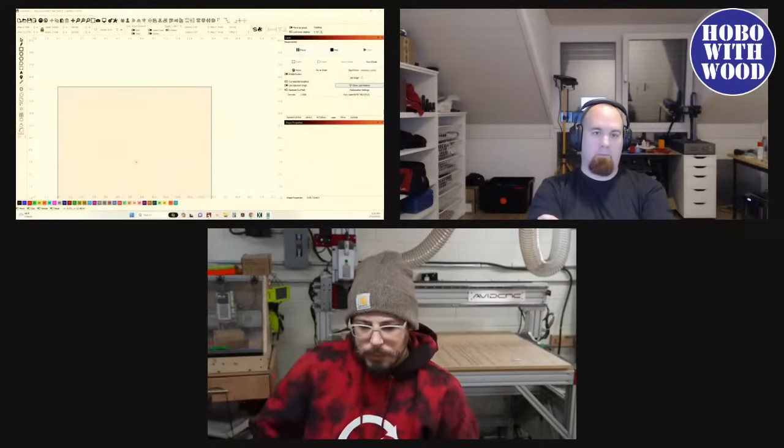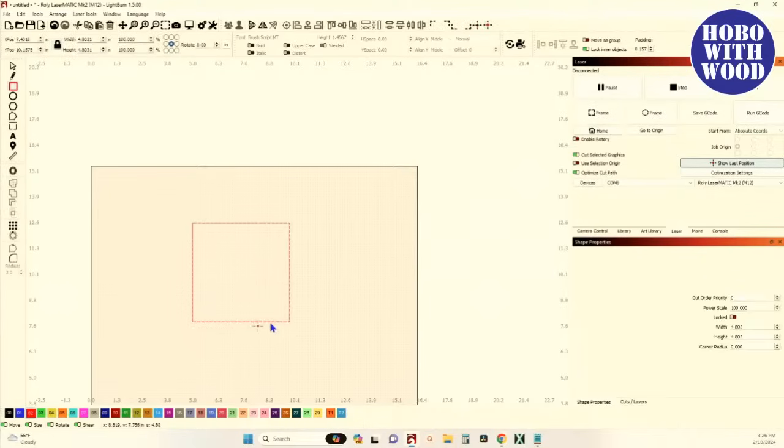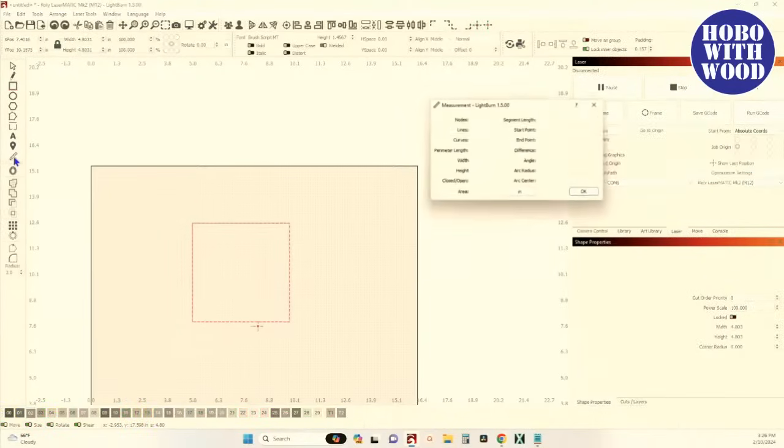All right. Measuring tool now has a snap to horizontal, vertical, and 45 degrees when holding shift. This is simple, but for those who use a measuring tool and need to be sure that you're measuring at a 45-degree angle: when you select your measuring tool over here and you want to measure straight across, you can just look up here and say, oh, well, that's 4.8 millimeters or inches, whatever.